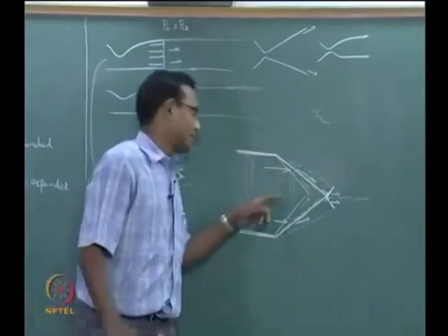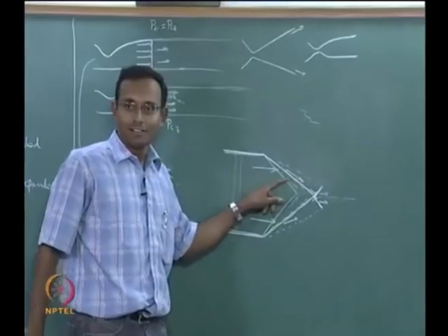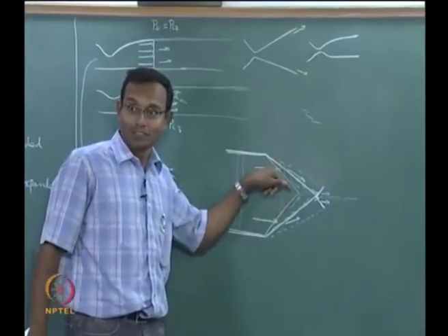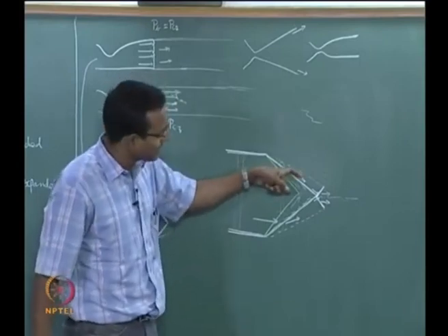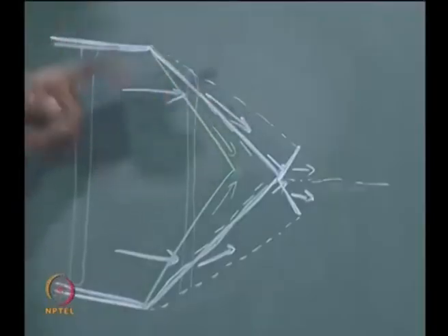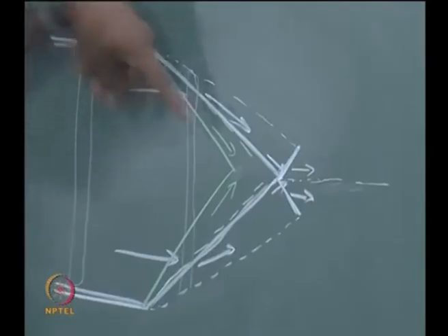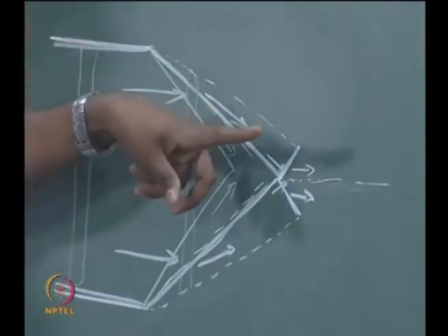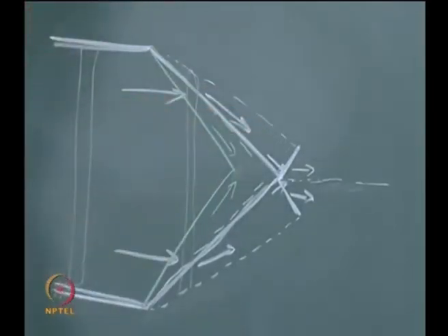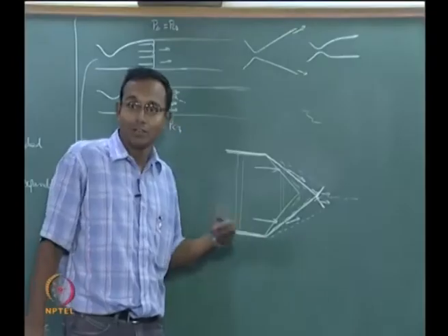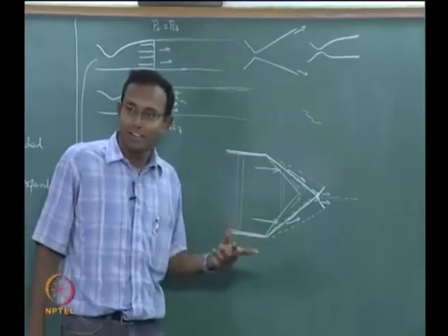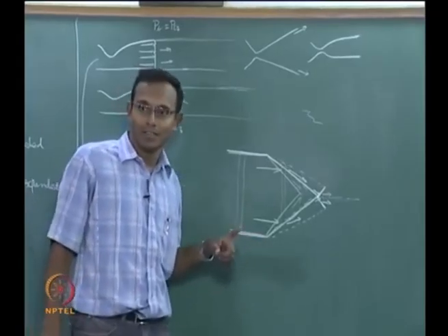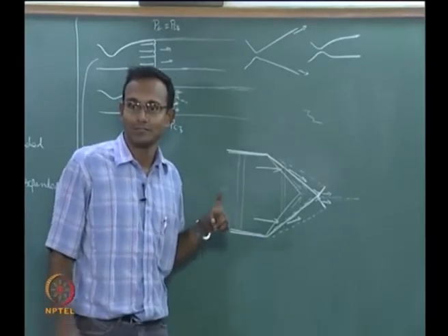But remember, stronger oblique shocks will have much lower Mach numbers downstream of them. So the Mach number downstream is lower compared to the previous downstream Mach number, and the angle that it has to turn by is now higher, right. A weaker Mach number flow has to turn by high amounts. Sometimes there will be a point where it will not be possible for it to turn by an attached shock.